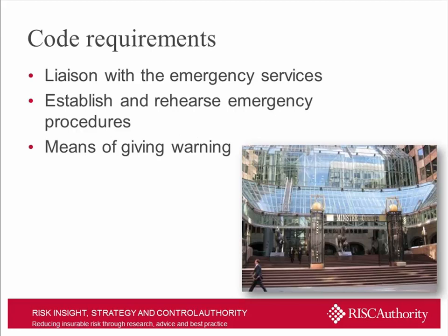We were just discussing the requirements for liaison with the emergency services. It's not just about familiarity, although of course that's really important. I think what you need to ensure is that the local crews do know where the site is, they do know what the access arrangements are, they do know what the principal hazards are, and that can be handled in a number of ways, through visits and, of course, the provision of information for them when they arrive on site that gives them everything they might need.